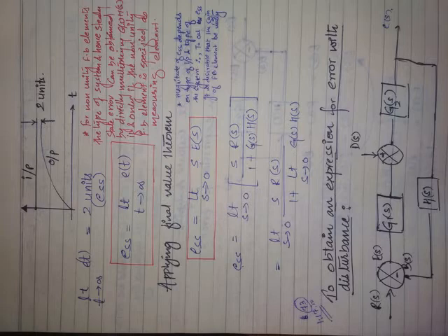And what information do you get from the open loop characteristics of a control system? Type. Steady state error's magnitude is now depending on the type of the input and the type of the system. That is why we have written that steady state analysis depends on the type of the control system. Understood? Yes or no? Yes.